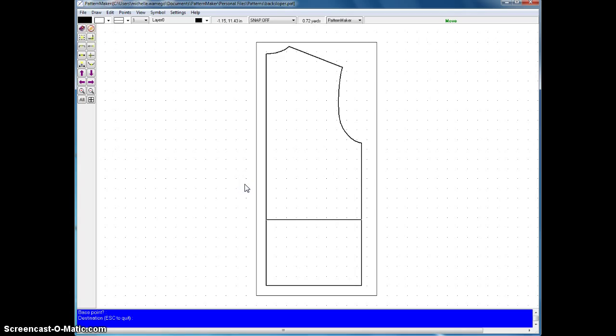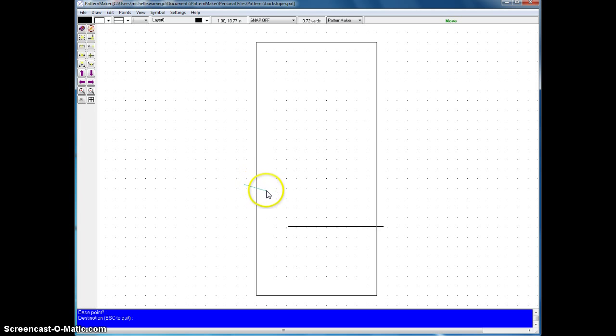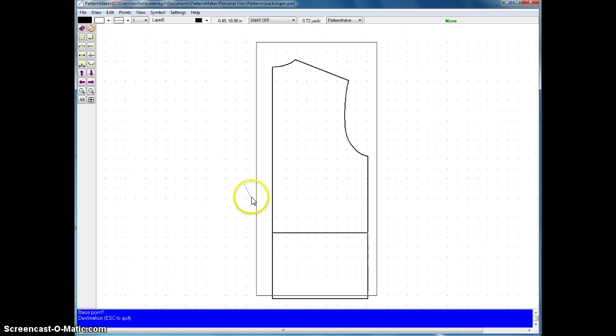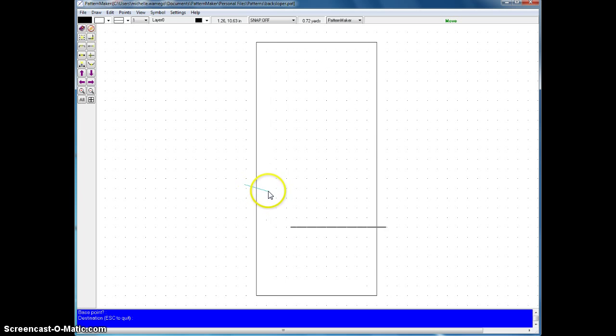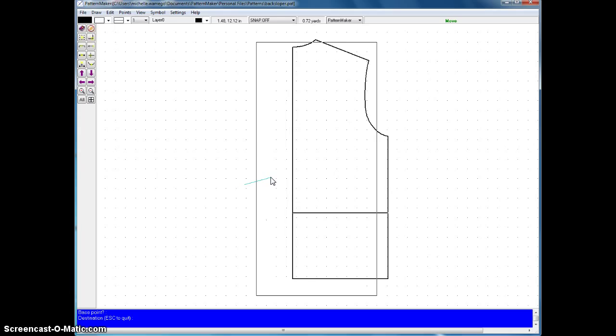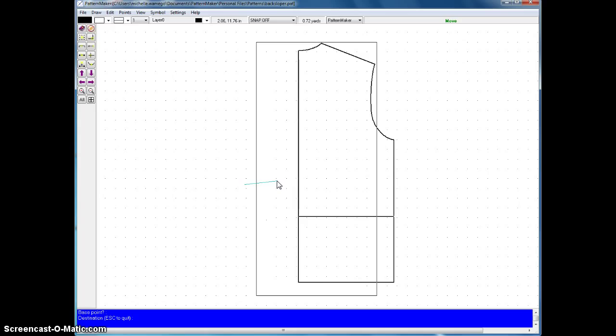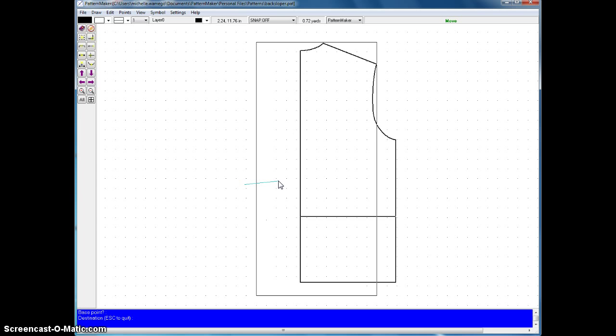The next prompt in our blue command bar will be destination. Move the mouse around. Remember not to hold the mouse button down. The objects you selected will move around too. You will see a blue cyan or blue-green line appear. This line indicates how far you have moved the objects, and it is not part of the drawing. Move the mouse to the right a bit, then click the left mouse button again. The cyan line disappears, and the word command is asking in the prompt line down here again.